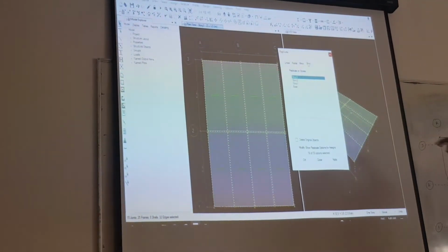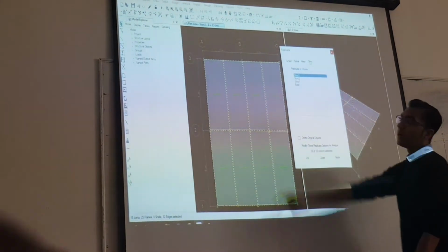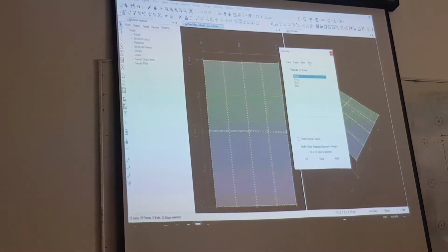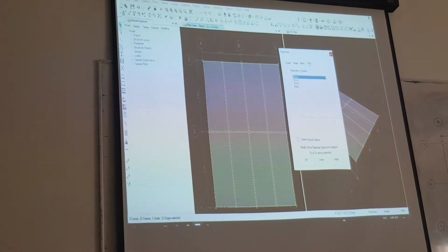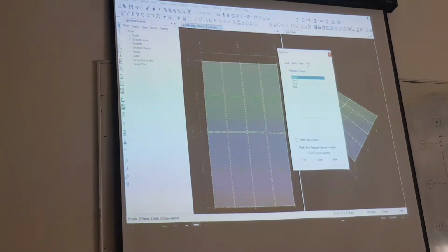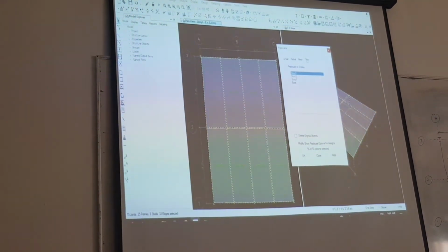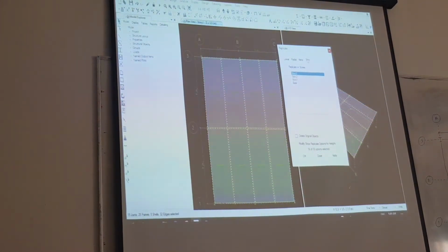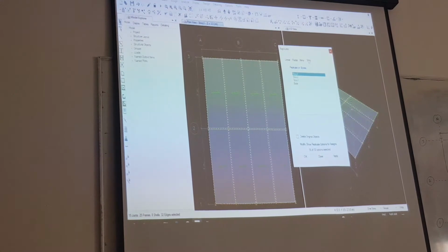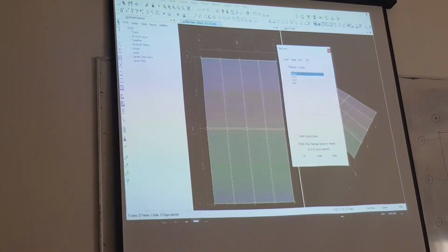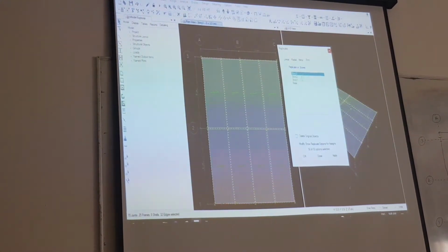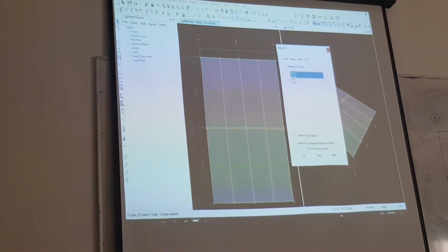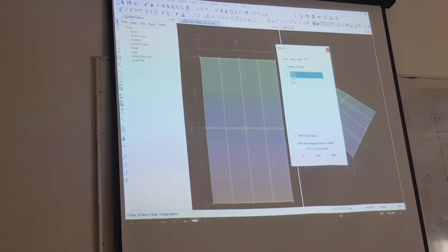So go to the story mode over here and be careful here. Please everyone see over here. You are already working on story 1, right? You have completed your work on story 1. This time, if you are going to replicate it, you are only going to select story 2 and story 3. So, select story 2 and 3. Everyone selected?